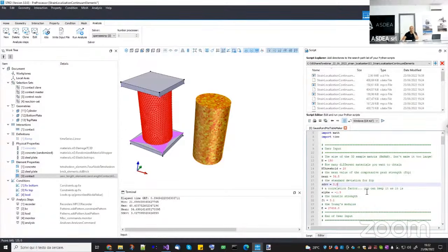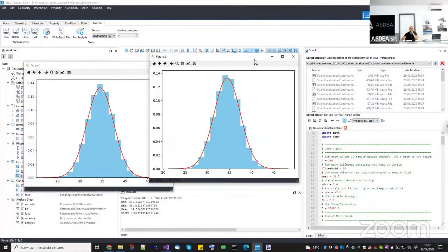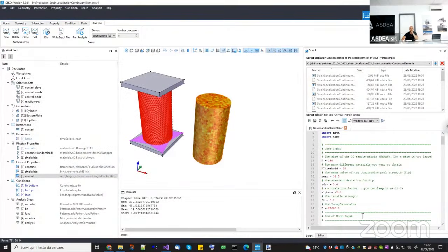So what it does is that it tries to group these uncertainties, these different material models, by proximity using a spatial correlation. I think the formulation that I'm using here follows a fractal noise like the ones that you can find in clouds or in material properties, and you can change it by this number. You can make this correlation higher by increasing this number, like if I use 2, you see here, if I use a larger number like 3. This one actually depends on the size of your problem, but you can do some tests.